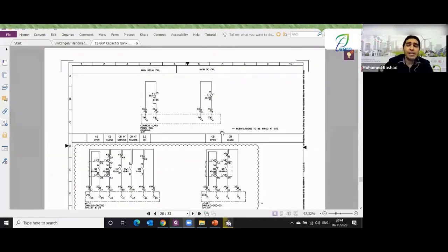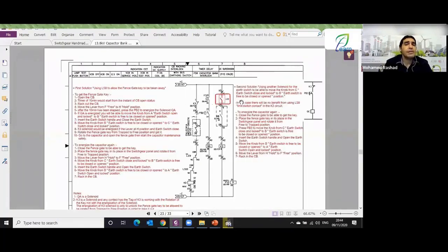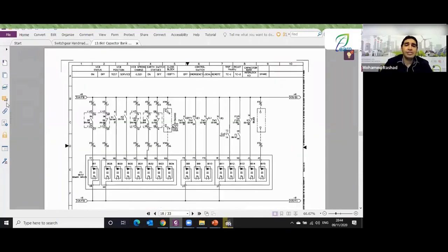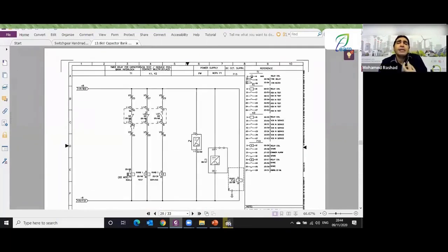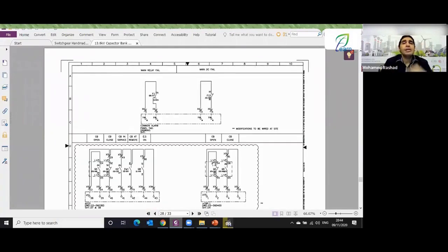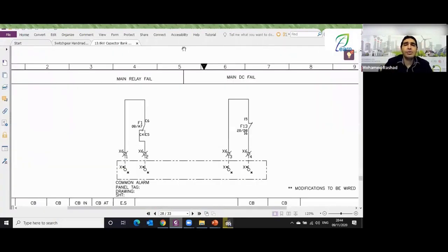At the same time, engineer, your relay circuit might be perfectly fine with no issues at all. The entire circuit is intact. However, internally, the relay's power supply circuit might have a problem, or its cards might have an issue. Here, engineer, we have something else that we call the main relay fault. Focus with me on the terms I'm going to write down for you here. It's called IRF, which stands for internal relay fault, meaning an issue within the relay itself.